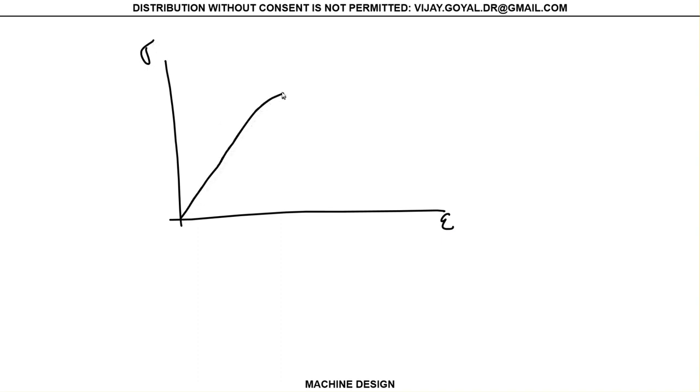So in this topic, we'll start the discussion on linear elastic fracture mechanics. When we say linear elastic fracture mechanics, we are basically talking about the following. First of all, we are assuming, if I can draw the stress-strain curve for you, that it's linear. You're going to stay in the linear realm, and you're going to be below your proportional limit.